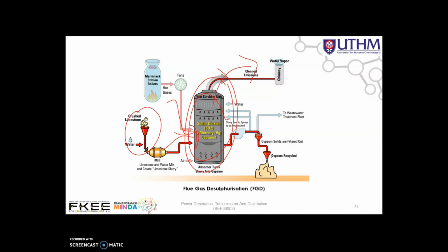It then produces the clean gas. After a number of chemical reactions, gypsum is finally produced in a suspension. After dewatering, this leaves gypsum with up to 10% residual moisture, which provides a valuable product for the construction material industry. So this is the overview of the FGD process.